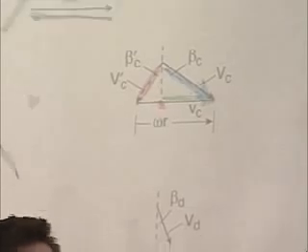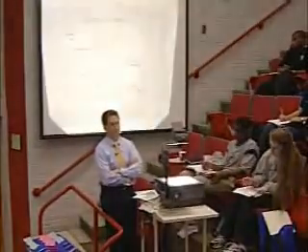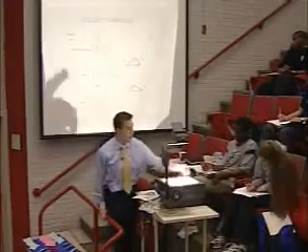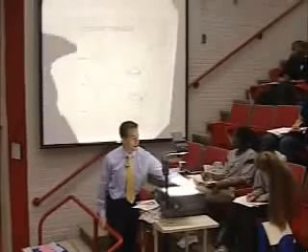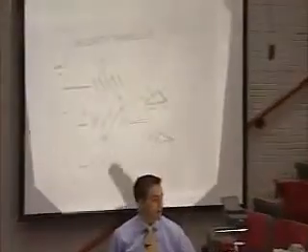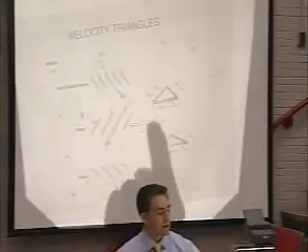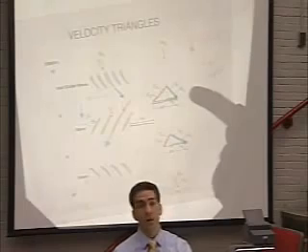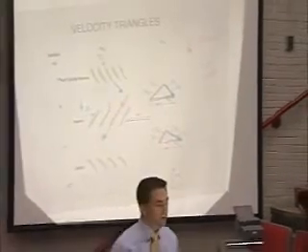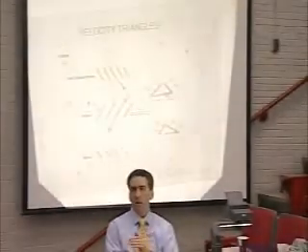Looks like before we had primes as our exit part, and the non-prime is our entry. Now, let me explain the nomenclature, which I wanted to stay away from a little bit. The A, the B, and the C are for whether you're upstream of this blade row, this one, or this one. So that's what the subscripts are. The primes mean that you're in the relative frame, so this is the relative frame velocity. And the unprimed means you're in the stationary frame. That's what the symbols mean. I wanted to stay away from the symbols for starters. So this is complicated. You're going to work a problem on this in a moment.